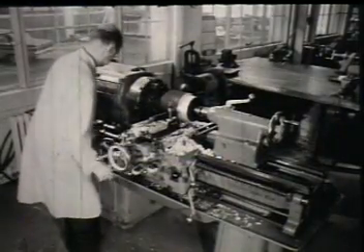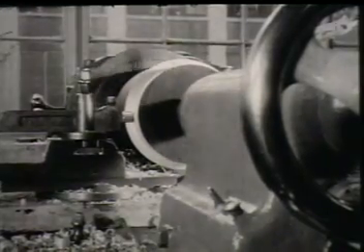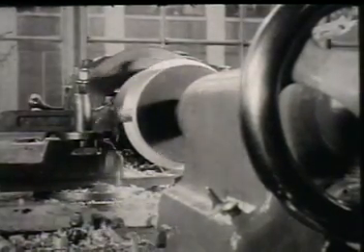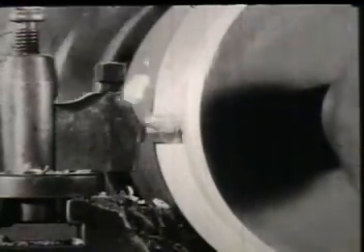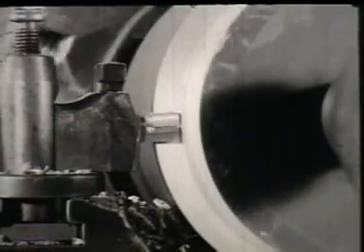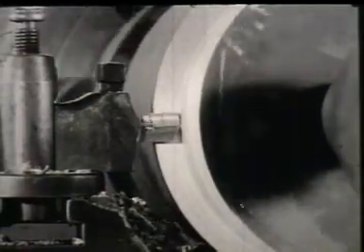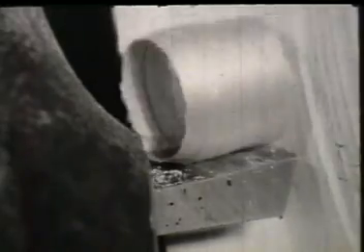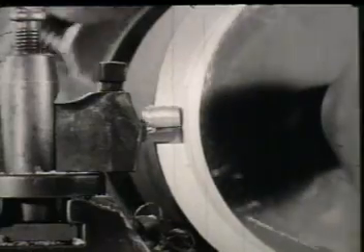However, it must be realized that most production machining is done at fairly high cutting speeds, so that the chip becomes hot. At very high speeds, the temperature of the chip will exceed its recrystallization temperature, and the chip will actually soften. Another noteworthy difference between low-speed and high-speed machining is that the built-up edge, which is so prominent at low cutting speeds, does not exist at very high speeds. Consequently, it can be assumed that the chip formation at high speeds is different from that previously observed through the microscope while cutting at low speed.